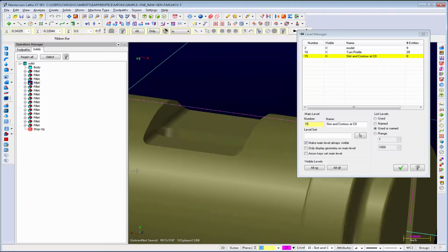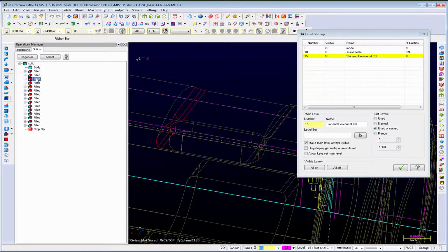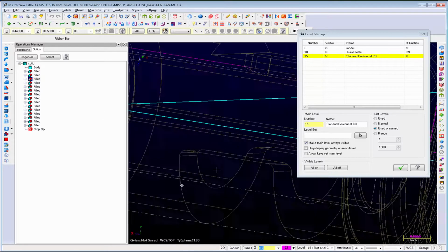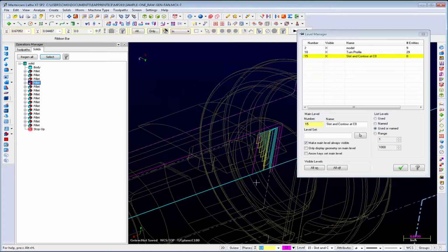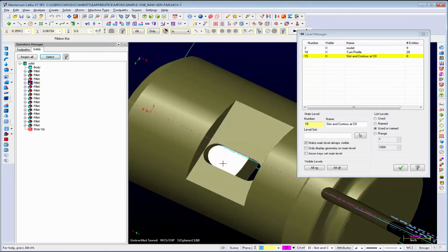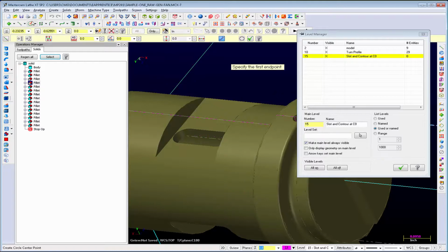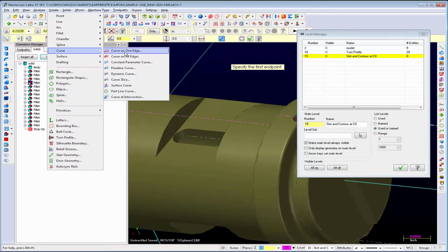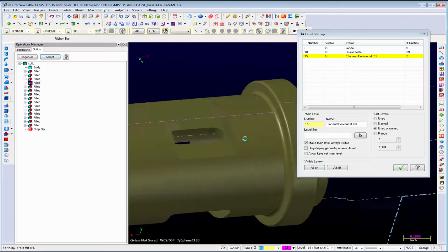Now, why did I do that? Well, I did it so that I could actually come in here and right click on the fillet and do suppress. And then over here, I'm going to click select, I'm going to find that fillet, and I'm going to do suppress. And what that allows me to do is get the intersections of those solid faces without having to create any temporary geometry. And now I can just create a curve on one edge, create those pieces of geometry, okay?